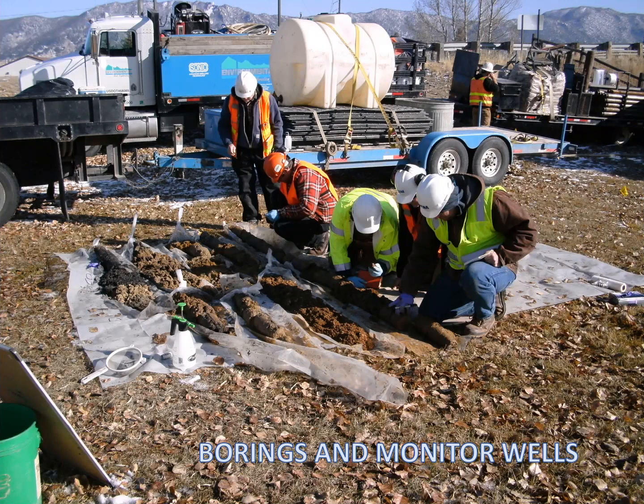You can put in enough wells and measure water levels and start to determine a potentiometric surface, so you can understand which way groundwater is flowing. And really importantly, and probably what's going on right here, is you can start to put together a stratigraphy of that aquifer.